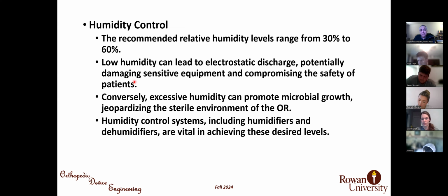Also humidity. Humidity must be between 30 to 60%. If there is low humidity, some electrostatic discharges will happen, and it may damage the equipment, and also it may harm the patient.